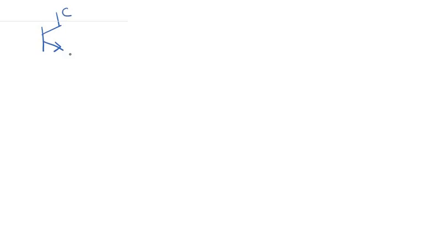As far as the transistor is concerned, we have three terminals here: the collector, the emitter, and the base. The base to emitter junction, we have already seen, is modeled by the small signal base resistance. So we have three points here: this is the base B, this is the collector, this is the emitter. The base to emitter junction is modeled by this resistor R pi. Note that this model is only valid for small signal or AC signals.